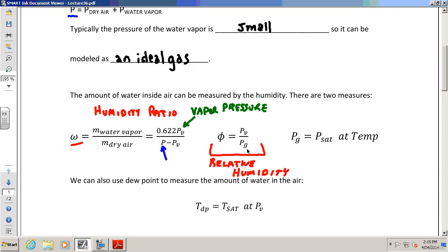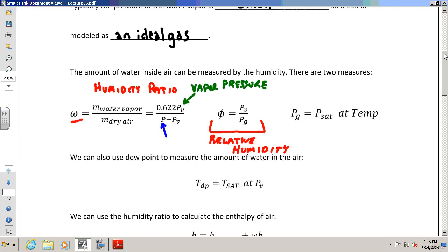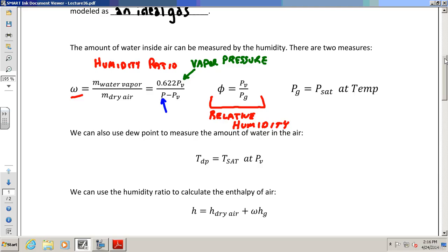Okay? So just because you have a higher humidity doesn't mean there's more water. You can actually have higher humidity and less water because of the temperature. So relative humidity is not a great measure because it can lead to a lot of confusion amongst people. But it is something very common in terms of measurement of humidity. Now the one that's a better measurement of the actual amount of water that's in the air is dew point. Okay, and that's another one you may have heard of.